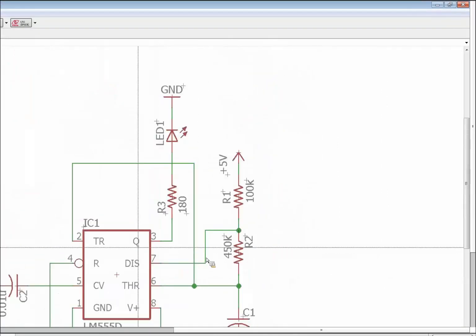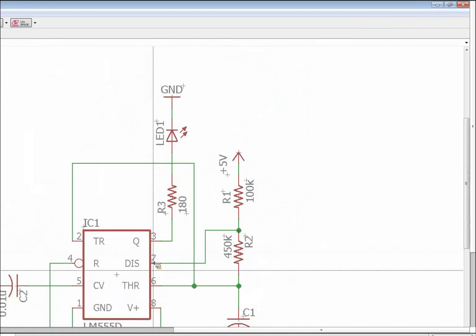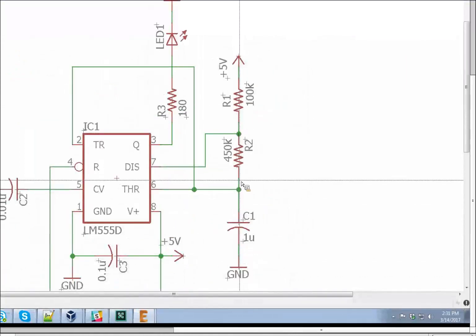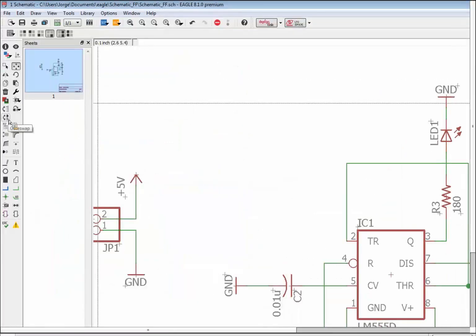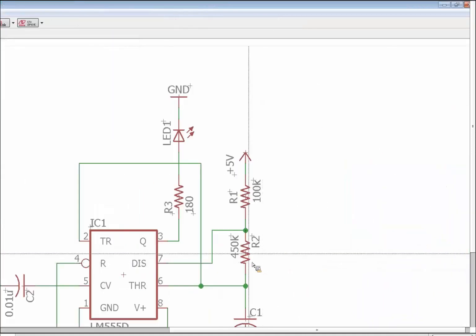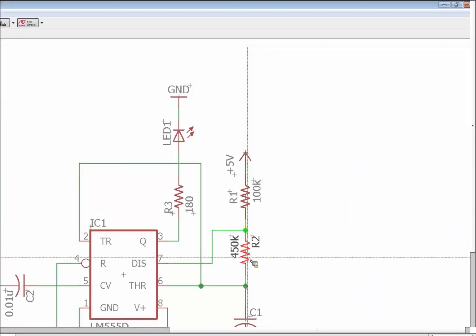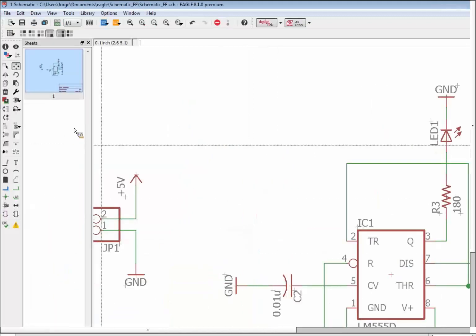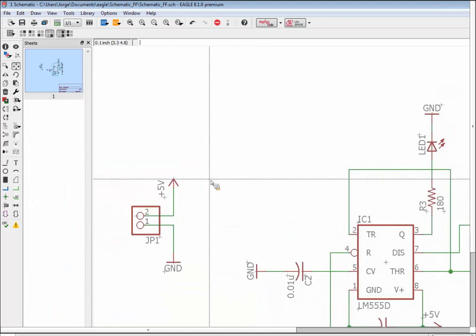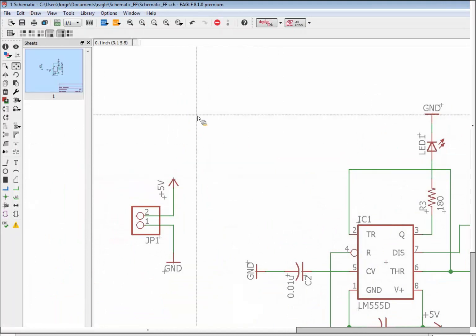But in components like op amps, or when you have multiple gates, like a quad AND gate or a dual op amp or something like that, you can also do gate swaps within your schematic. If later on looking at the layout you find that it would have been easier on the layout to use this gate versus another, you can always do gate swaps in the schematic. So that's a pretty handy feature that you guys can leverage. Anything else that I could go into would be a bit more advanced, like hierarchy and things like that. So I think we could call it here.